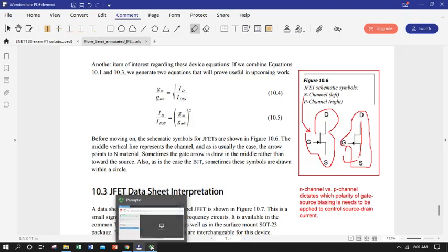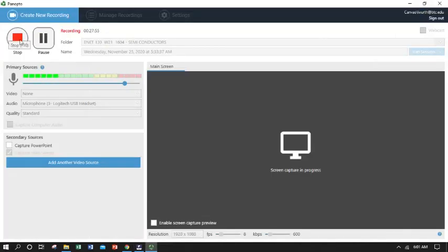And that is it for junction field effect transistors, as well as general theory of field effect transistors generally. Next lecture we'll go into a variant on this, insulated gate, very similar with a few little exceptions and a little bit additional functionality, and that will conclude our study of field effect transistors. We will not be applying them in circuits the way we have BJTs, but know that basically the same kind of amount of circuit control can come from them. But basically, anytime you have a field effect, you will use a voltage signal to control current rather than a current signal to control current as in a BJT.